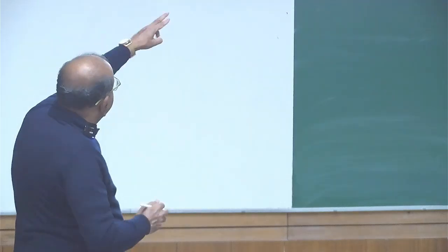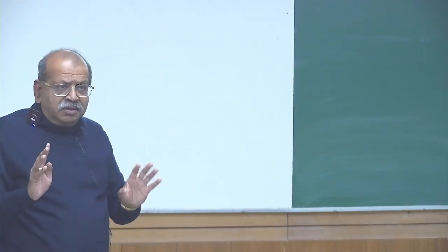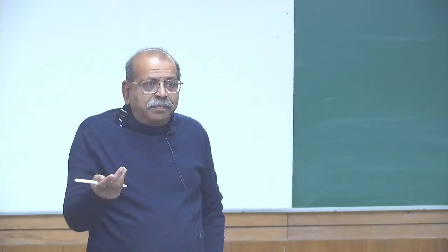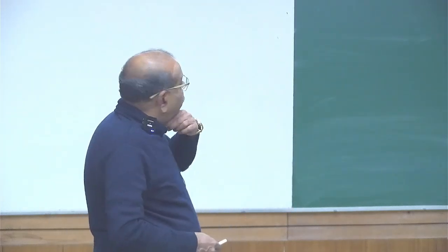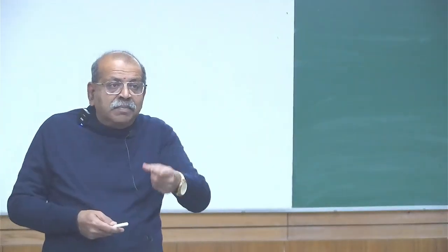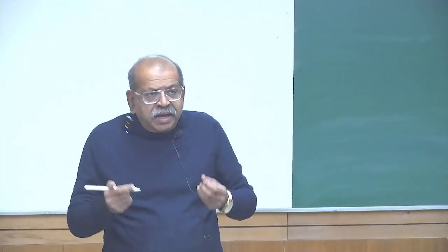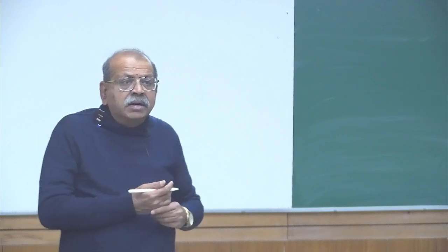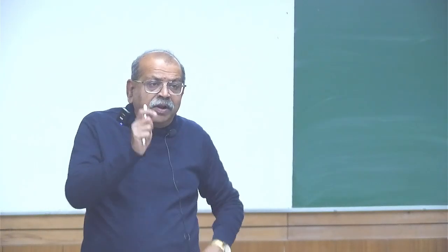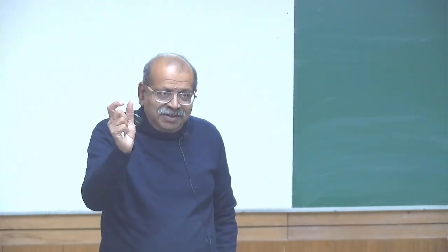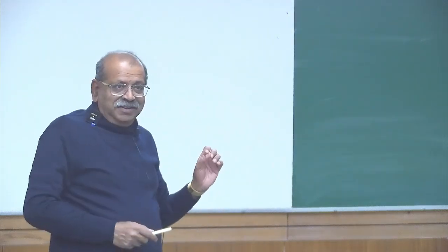The only place where this will not work is if there are body couples. Then the body couples will be of the order of the couple multiplied by the mass of the element. And so there, if they are of the same order as tau xy, then this may not hold, because when you multiply by volume, it will be delta x delta y times 1, which is the same order as the left hand side.